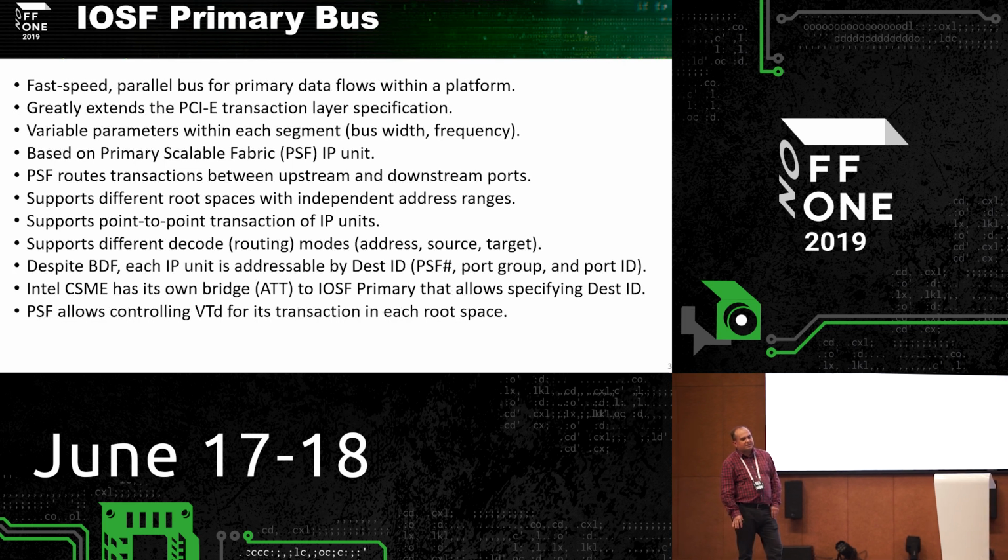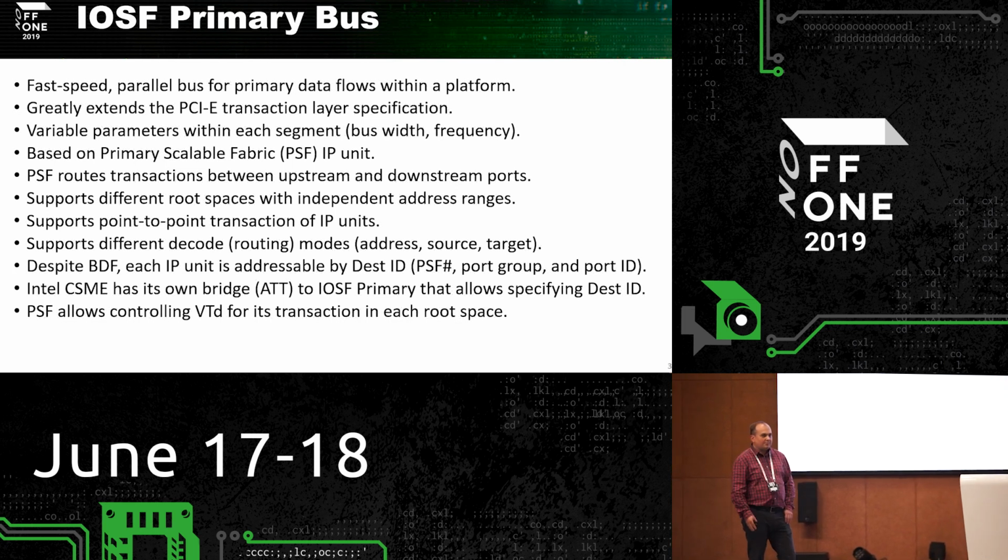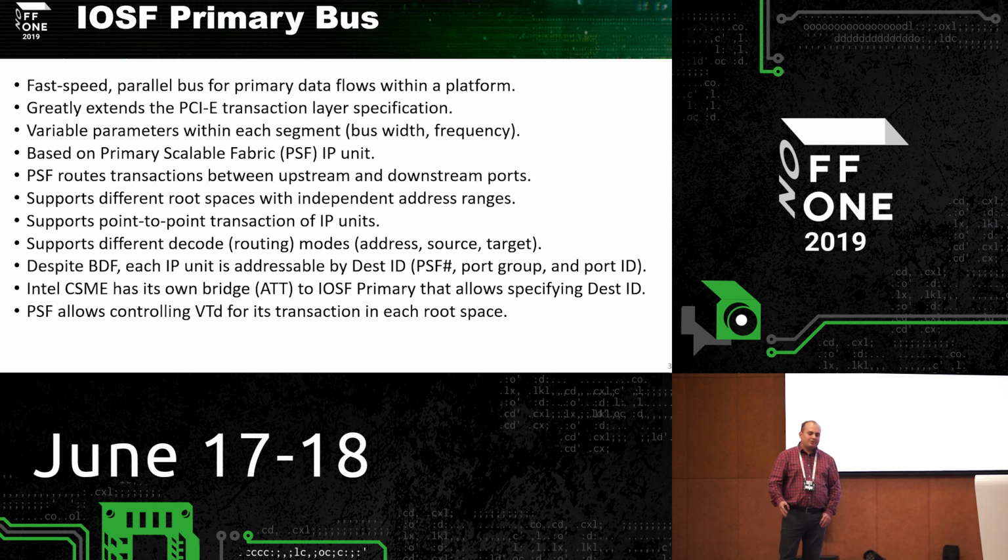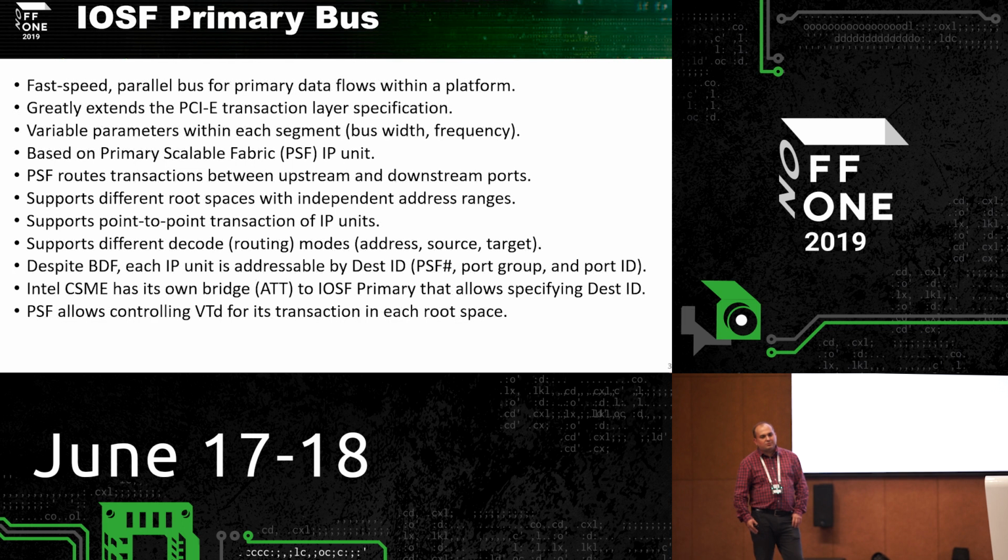So the IOSF primary bus is intended, and by the way, we got a part of this information from Intel patents, but to take a look at it live, how it works in runtime, only became possible using Visa. So I can say that it's been designed to control all the main data flows within the chip, within PCH, within the system on the chip, and modern CPUs.